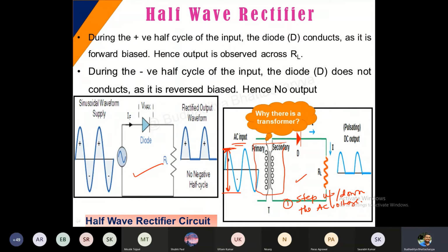So you are affecting your rectification efficiency. If we calculate, we'll do that, you will find that it comes to around only 40%. So you are feeding in 100% of AC input and getting only 40% of the output. So basically 60% of your generation is completely lost. Understood? In that way, the process of half wave rectification is not a very good solution.